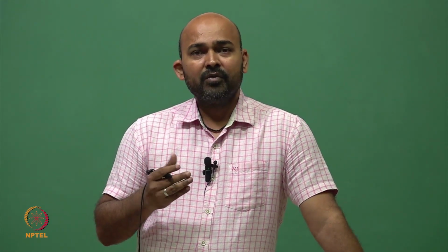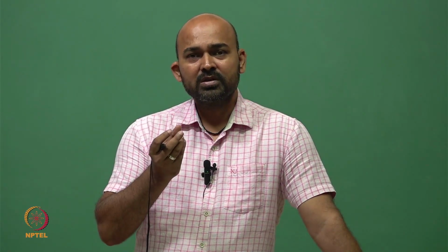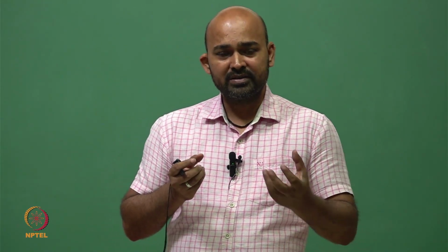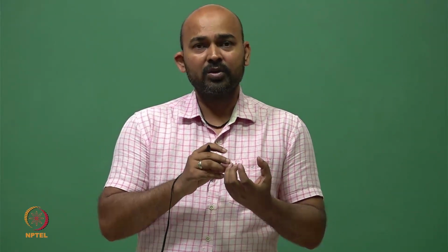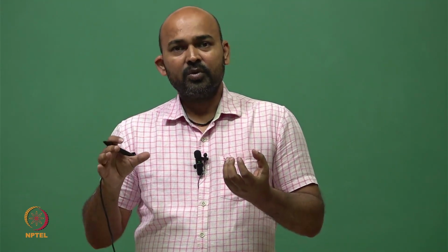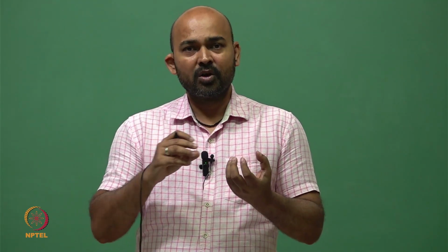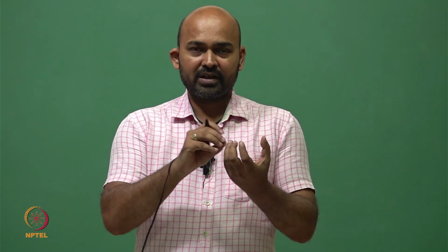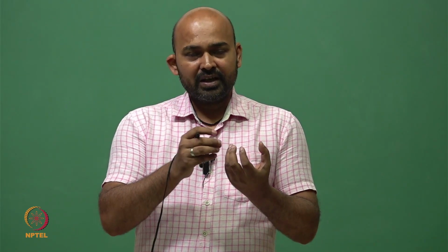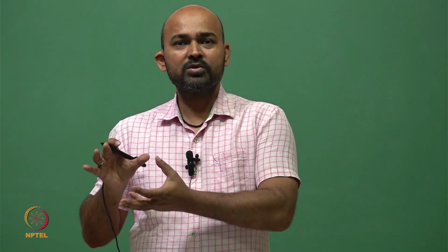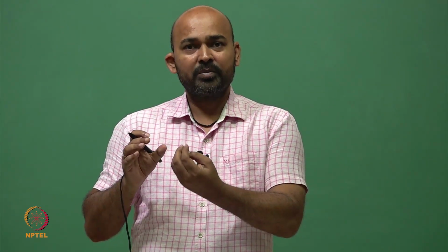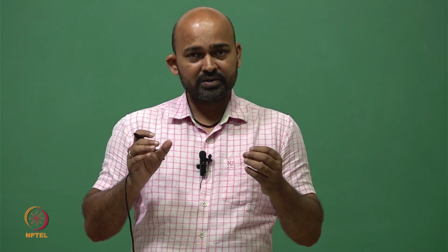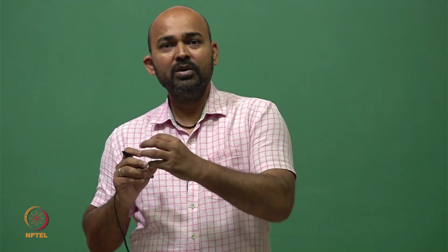If we want to get rid of this problem, we can use some optical devices. Like, we have a microcontroller. Now the signal of this microcontroller goes to the motor as an optical signal, not as an electrical signal. So there is a transmitter, for example an LED, which sends the signal, and this optical signal goes to this motor which is running at 1000 volt. This has an optical receiver. Now this optical signal goes from the LED to the receiver.